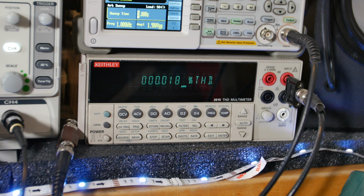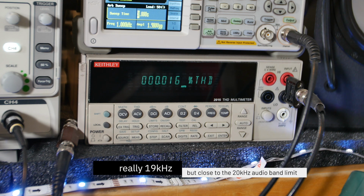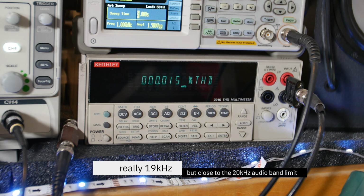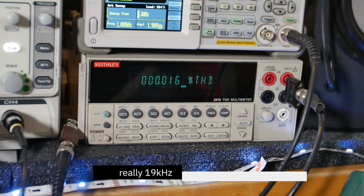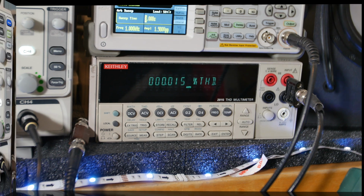And by the way, we're going out to the 19th harmonic, which is around 20 kilohertz. So that's measuring across the whole bandwidth, because the fundamental is at 1 kilohertz. So that's going out there. So that's pretty good measurements, right?